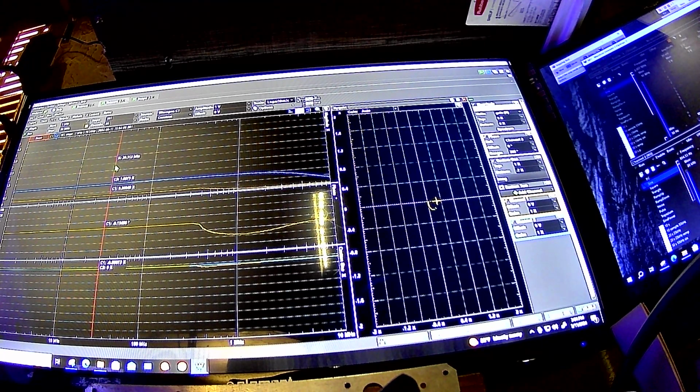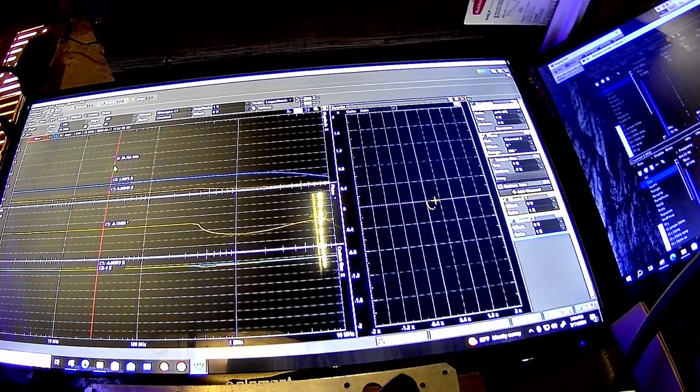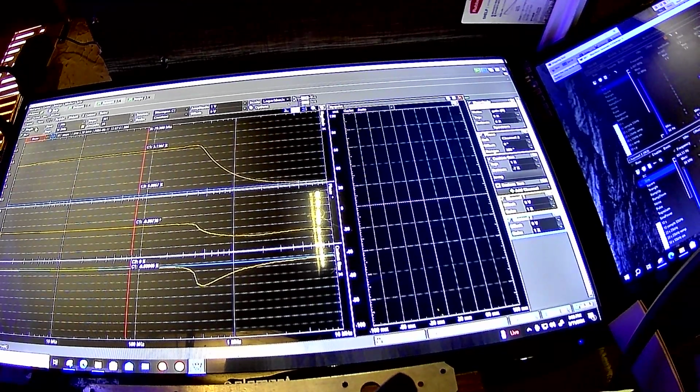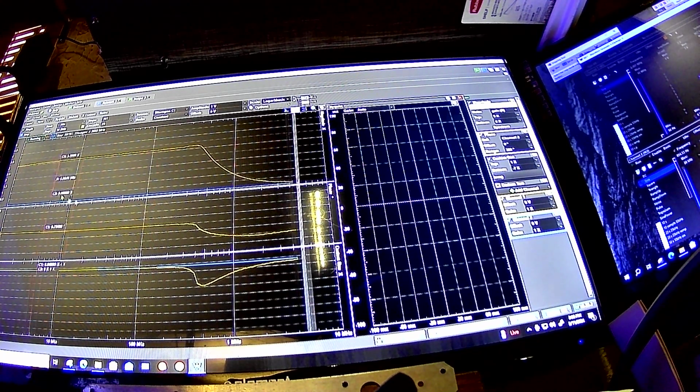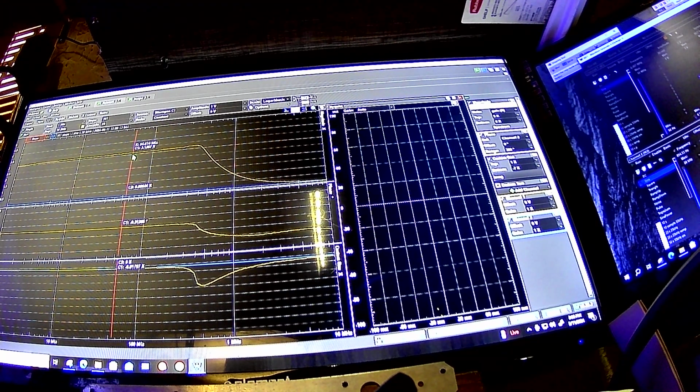Let's see. Well, hold on, let me mess with it for a second. Okay, I set both the probes to 10x. It wasn't working for some reason when I tried it last time. But yeah, so not getting any range warnings, but you can see, it's still using our blue line as a trace, even though it's a tenth of a level. But we're still getting accurate gain readings because that's all we care about. Is the gain.